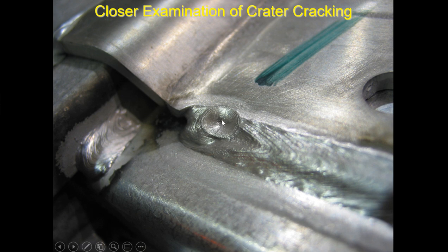Now, in this particular case, even though the weld is as perfect as can be almost everywhere, it started to stall a little bit here, and you can see this contact tip was giving us trouble. It held the wire back. There was a quick fuse right there, but then it started up again here. Then the weld wire and voltage tried to shrink, and that's what happens right here. The wire stuck again, and then I just had a bit of an arc, and I didn't get my fill. So there goes the robot.